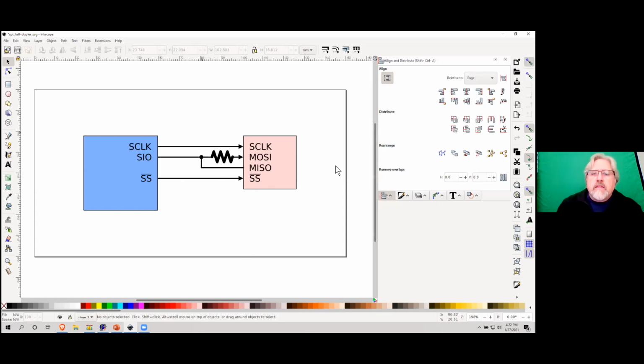Now, hey, John. Yes. One thing about the SPI flash chips is that if you look at their timing diagrams, according to the state changes, they will never create a conflict. And if you kind of do the dance with it, you can actually get rid of the resistor in applications where you want to just talk to a flash chip over 3 pins. Okay. But it is outside of the normal protocol, but the memory chips will work that way. I am of the opinion that resistors are cheap insurance. So I always put the resistors in.